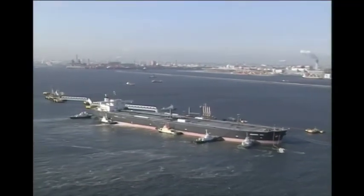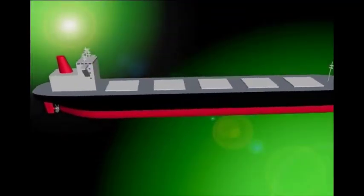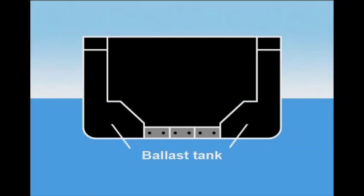First, let's look at what ballast operations are and their purpose. Since a ship's draft is shallow while in ballast condition, it's susceptible to wind and wave impact. As a result, rolling increases and hull stability deteriorates. To improve hull stability, a ship's ballast tanks are filled with seawater.